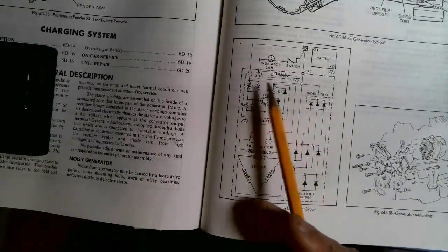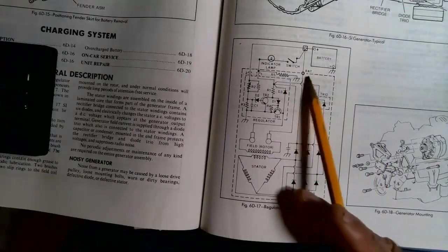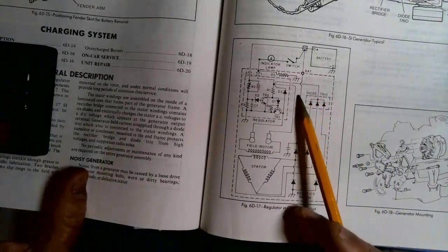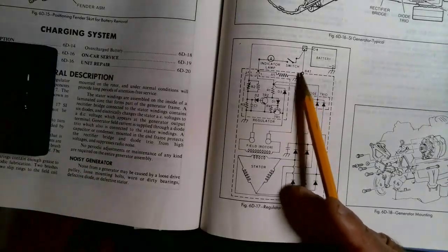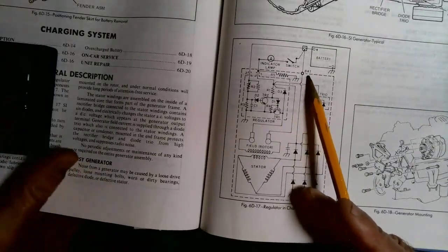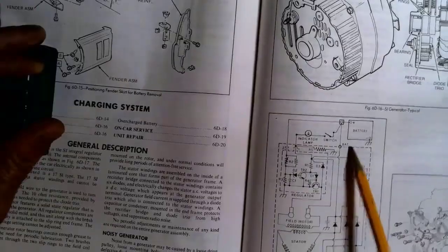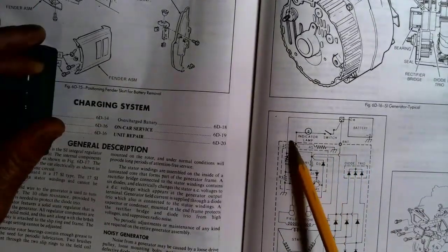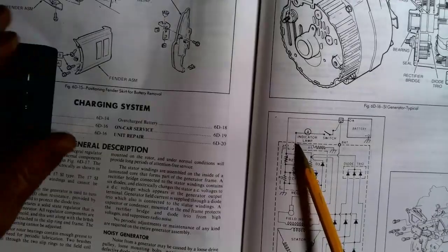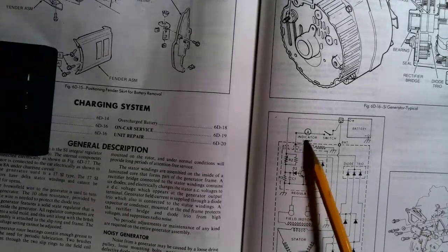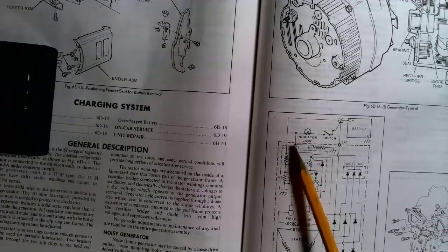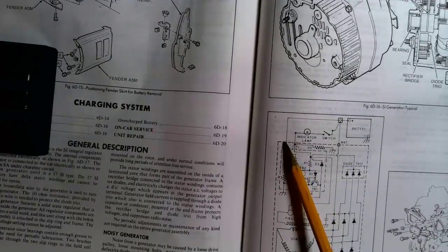All right. In terms of the interface to the vehicle, there's the battery terminal here. This is the output. This particular car has a 108 amp alternator. That's where the 108 amps comes out, out that battery terminal, and that's this stud right here that sticks out the back. That's where this wire attaches. And then there are two other inputs to the alternator. One is for the idiot light, the generator light that tells you your alternator is not working if it fails. That connects here. And then this is the sense lead. The regulator needs to know what the system voltage is, and this is the lead that it looks at to regulate the output.